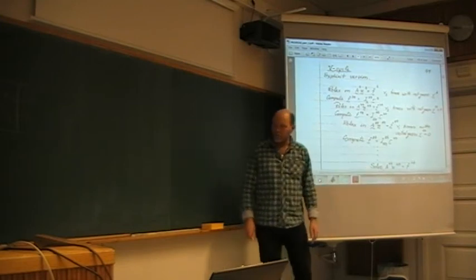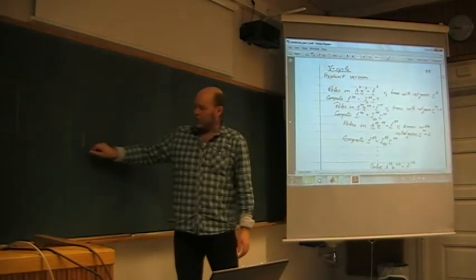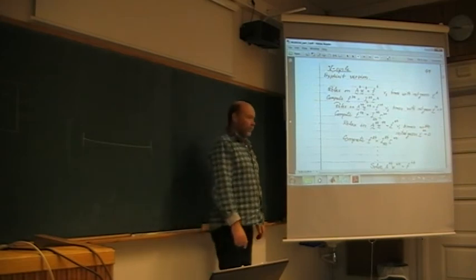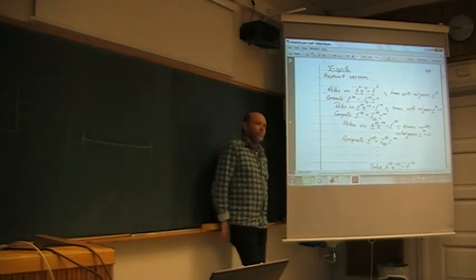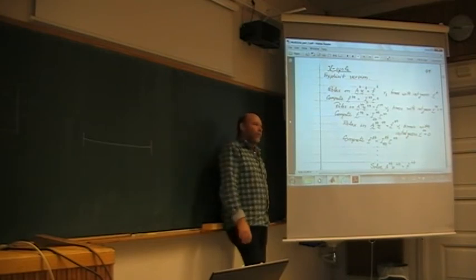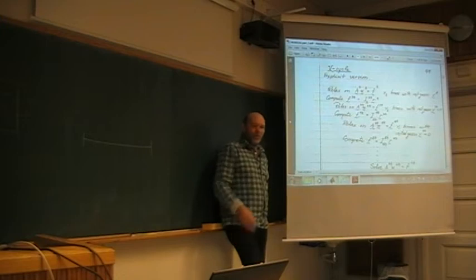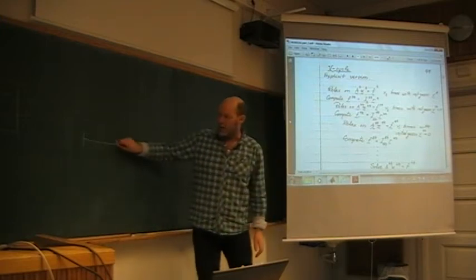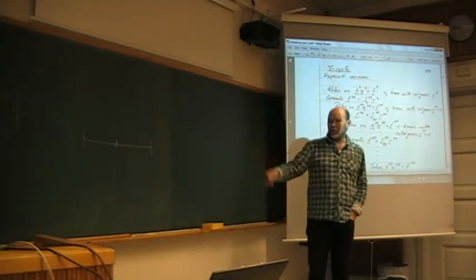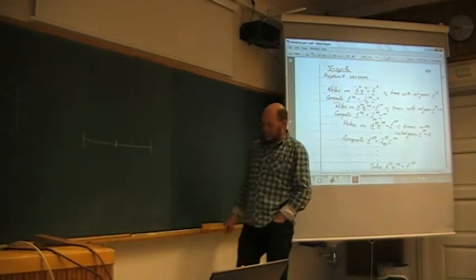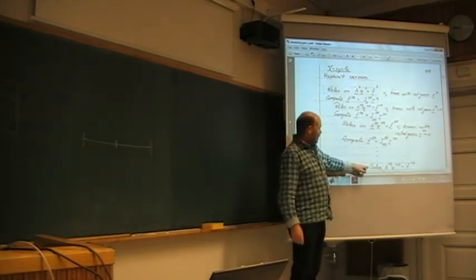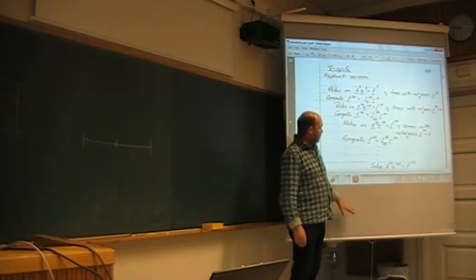And if you're lucky, when you have your fine mesh, if you choose 11 points or 101 points, you can't divide them into anything. So of course you use 64 points or 256 points. Then you can zoom all the way down till you have one single mesh point, one single grid point. And then you can easily find the solution directly, no problem, on the coarsest mesh. And then we are going to go up again.